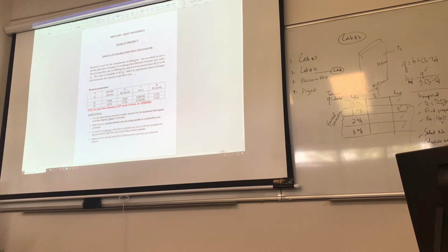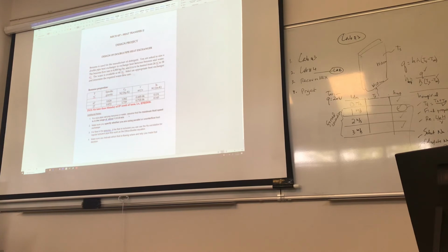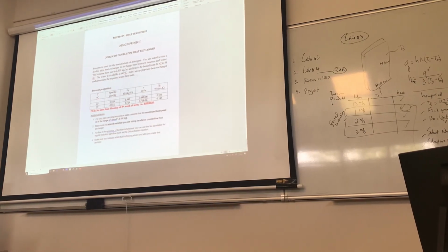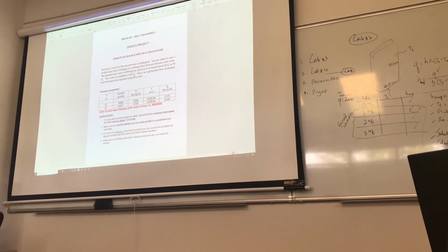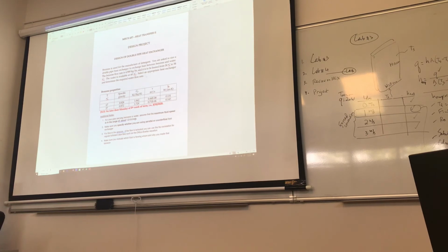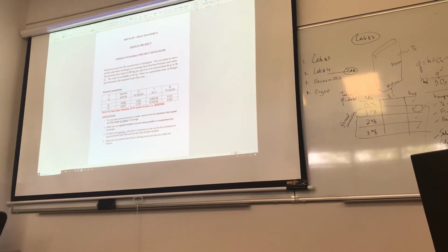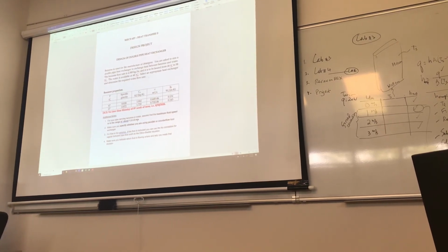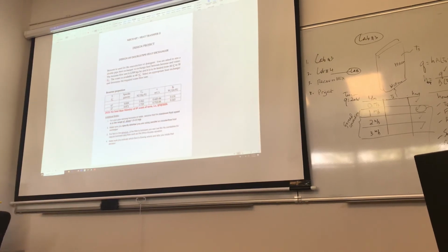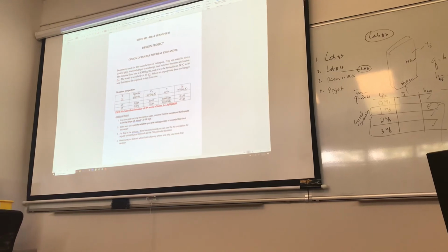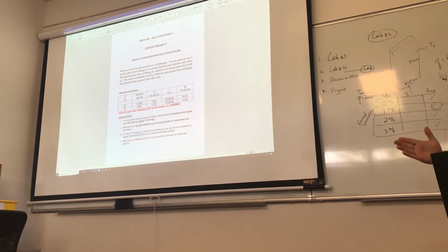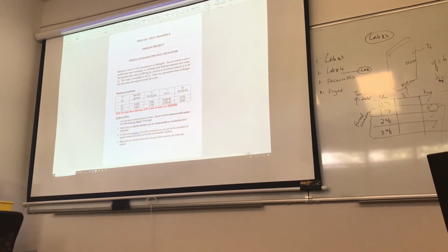Now, for your pipe carrying benzene or water, assume that the maximum fluid velocity is in the range of 1.2 to 3. So I don't want to see a flow in either of those pipes outside that range. Always try to start somewhere in between. I've seen some people go to the edge and then find themselves outside of the range. So play it smart.